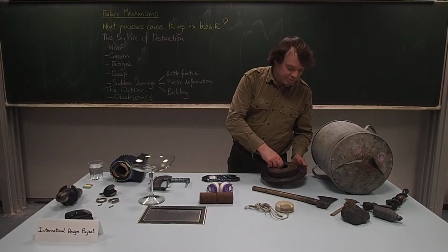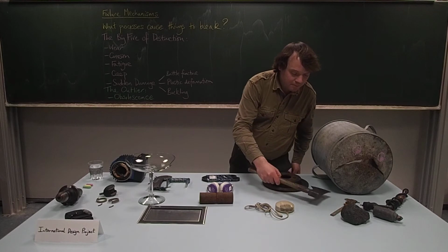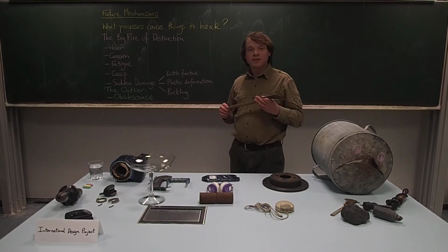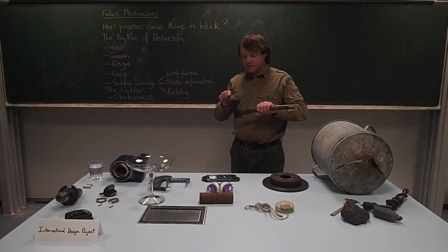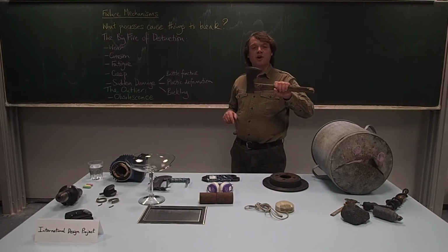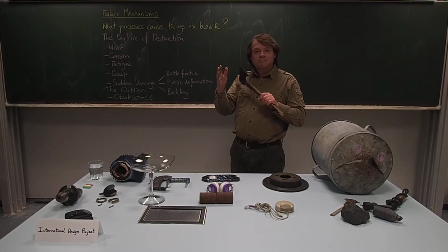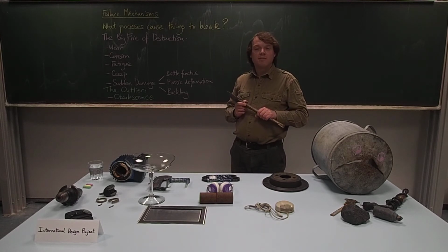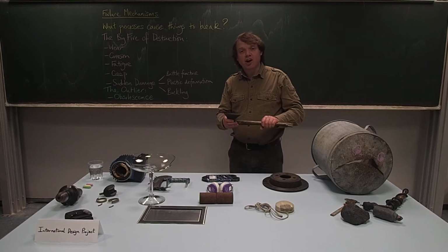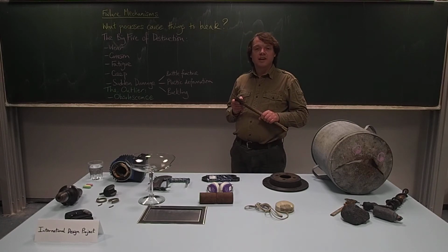The other kind of things that can be affected by wear: here's a very old small wood cutting axe, and you can see the cutting edge is no longer so sharp, because it's been worn, some has come off, some has got deformed, that sort of thing. And now and then you'll need to take it to a grindstone and sharpen it to restore the cutting edge.